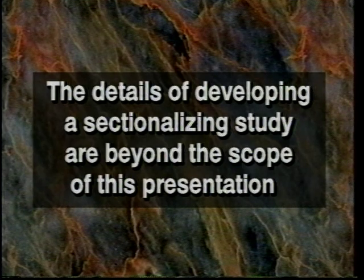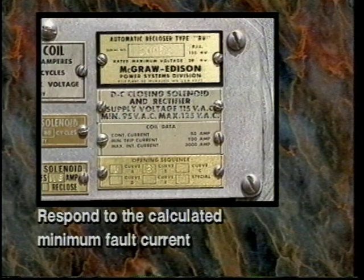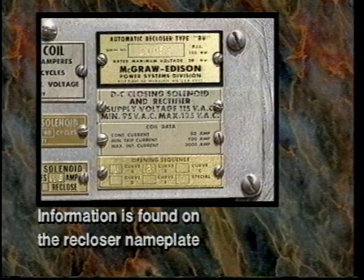The details of developing a sectionalizing study are beyond the scope of this presentation. The line reclosers must be designed to carry full load current, respond to the calculated minimum fault current at the end of the line section it protects, and be able to interrupt the maximum fault current at the recloser location. This information is found on the recloser nameplate.